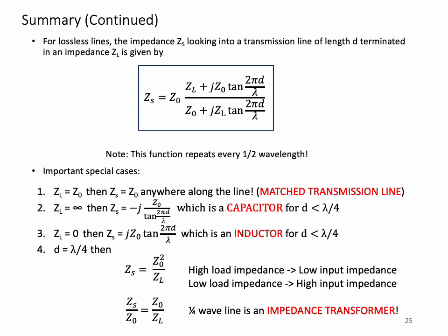Finally, the most important one for our J-pole design and analysis is the case when the length of the transmission line is precisely equal to a quarter wavelength. In this case, we see that the transmission line acts as an impedance transformer. High impedance loads get transformed into low impedance sources. Low impedance loads get transformed into high impedance sources. And this will be very useful, as we saw in designing the J-pole to operate on multiple bands.